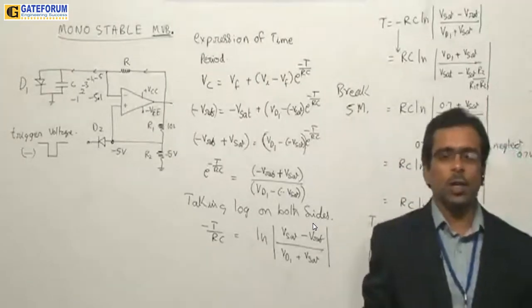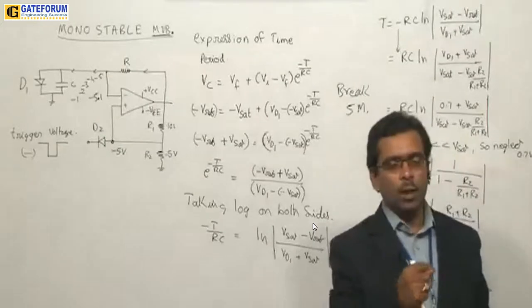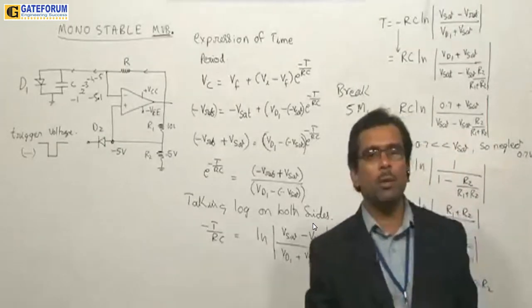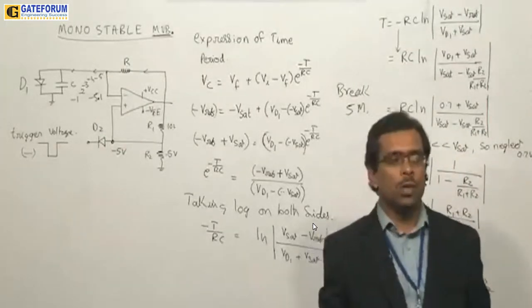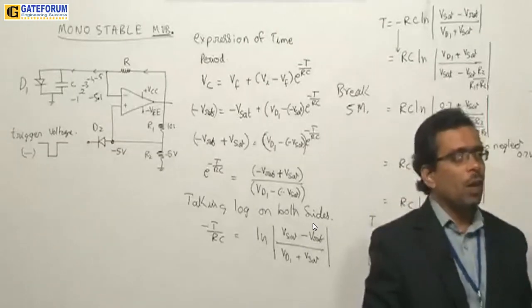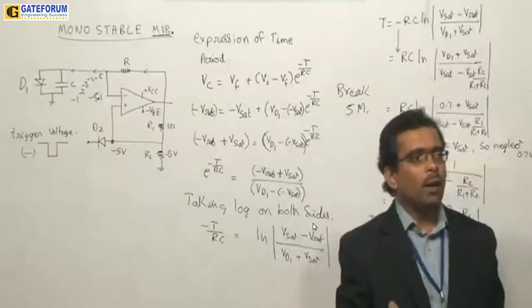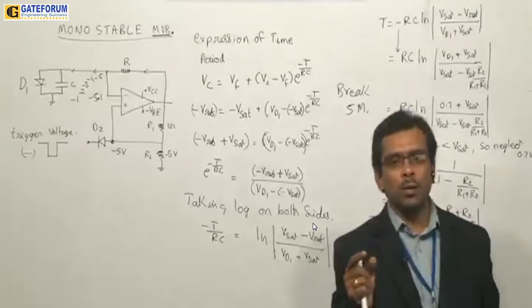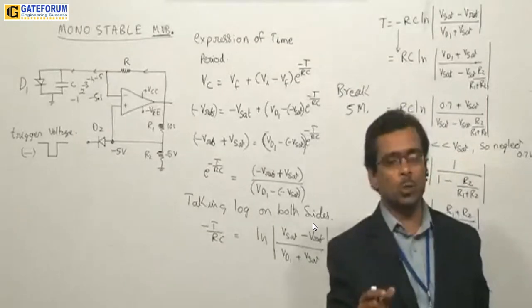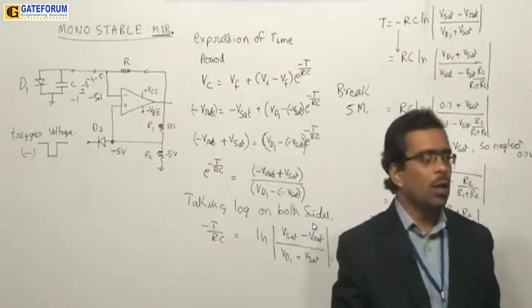So you will not get those spikes. Only in the differentiator circuit that we have studied do you get them, because of the design and the discharge path we provide for the capacitor. Here we don't do that. But one thing I can comment is that if you put the capacitor very small, you will get a smaller pulse width. That is what you are going to get.